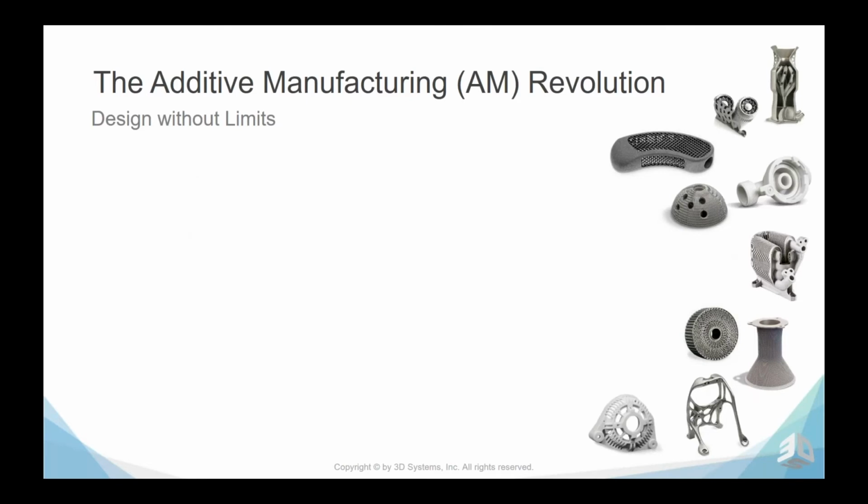So we got used to seeing this title, the Additive Manufacturing Revolution, but what really makes additive manufacturing a revolution? Additive manufacturing is a revolution not because it is faster, cheaper, or more efficient manufacturing technology. In some cases it is, in some cases it does not. It is a revolution because it enables us to produce geometries that could not be produced before using traditional techniques. So when looking at additive manufacturing, we should not look at it as a way of manufacturing the same part by simply replacing subtractive techniques with additive ones. Look at it as a way to explore opportunities that cannot be addressed by subtractive techniques. Look for savings that are not necessarily direct savings, like the cost to manufacture the part itself. Look for savings that are derived from the enhanced functional properties that you gain through the new geometry.